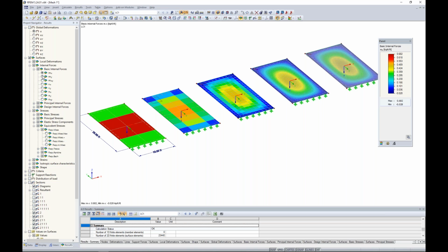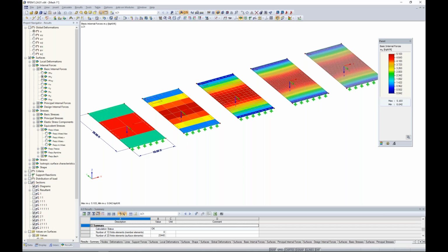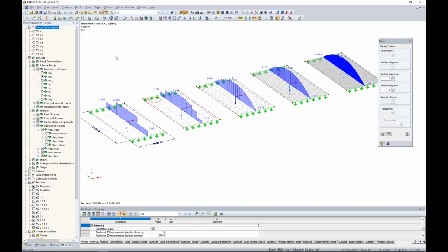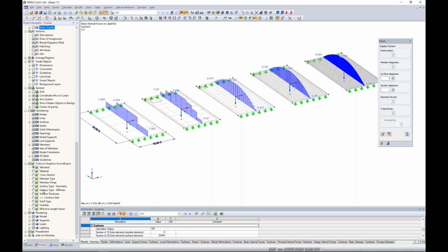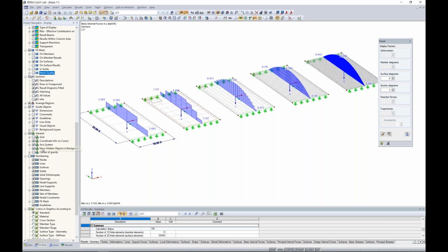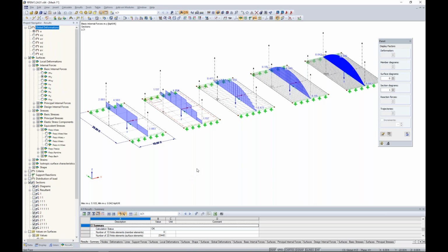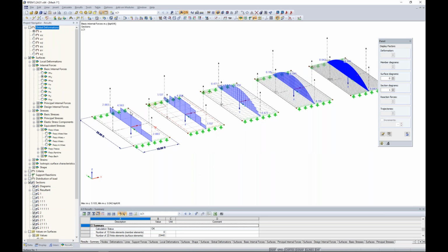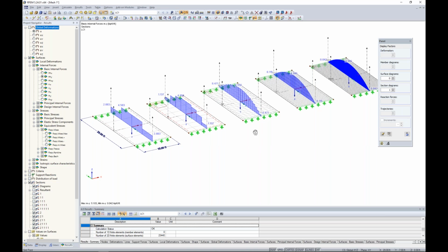Now we can compare section cuts as well. I'll turn on these sections and turn off my ISO band so this is a little easier for you to see. I just made this cut right down the center of these surfaces. Under my display tab, let me also turn on how those cuts were made. I'm currently looking at the MY force, so again along the length, and you can see how the diagram of this section cut changes.